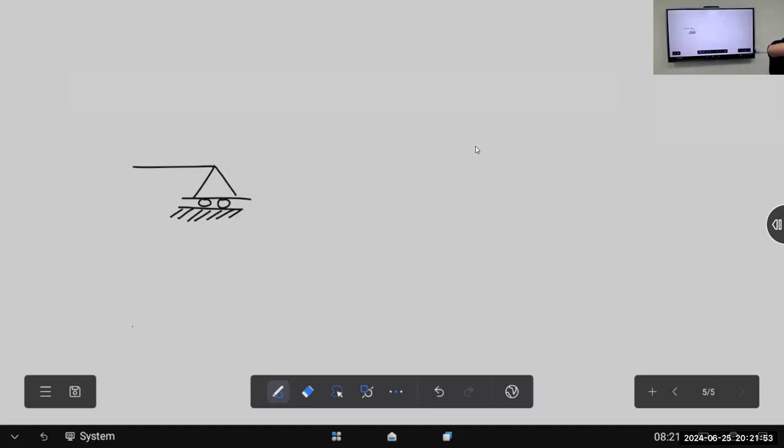Once you work as a structural engineer and you see this figure, I will know this is a roller support. A bridge, steel bridge or concrete bridge, supported above a beam, you will find roller support. Two big steel cylinders. What is a steel cylinder? Roller support. The reaction is always perpendicular to the moving plane. Now this is the reaction. We have one reaction.